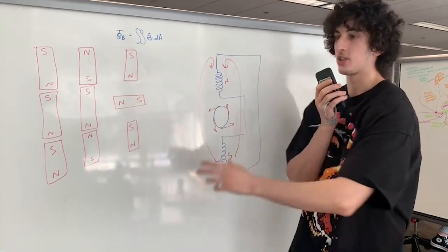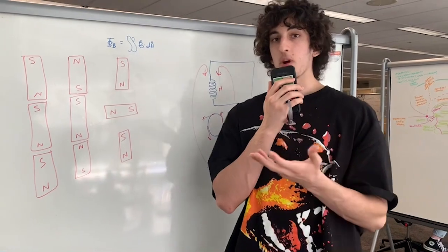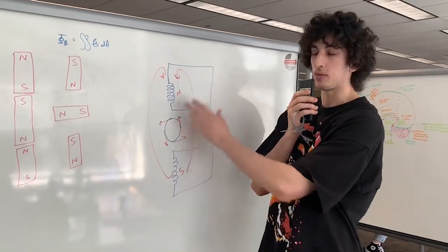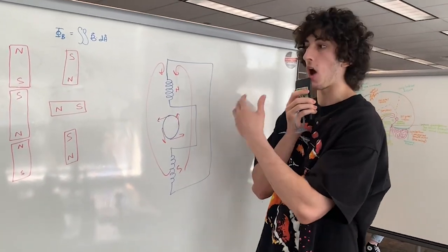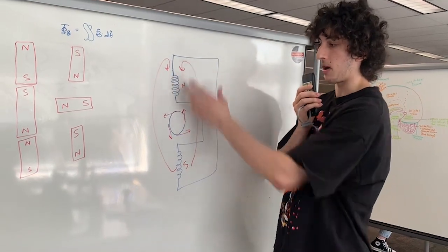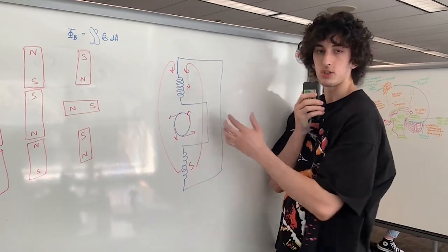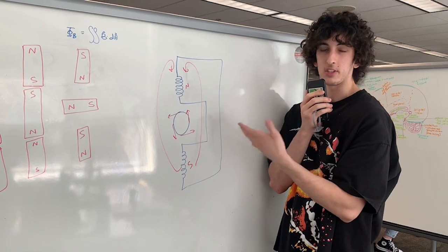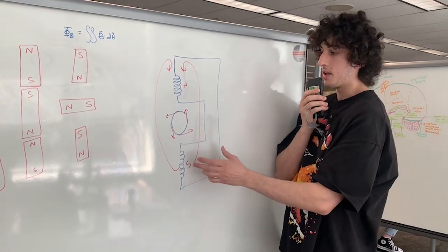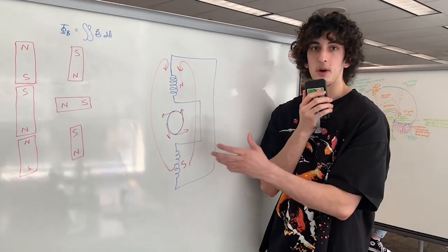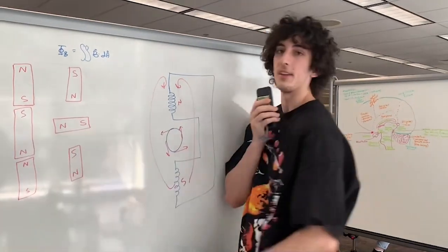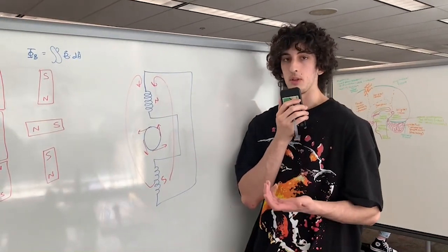Another small thing is that you also need to offset the phase angle for when you start each current. All currents from each of these sets of inductors are going to be different. They're going to be started at different times, because if you don't start the alternating currents at different times, then the motor can jam as well, because it can end up in a stable or unstable equilibrium.